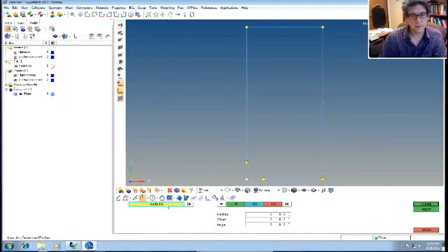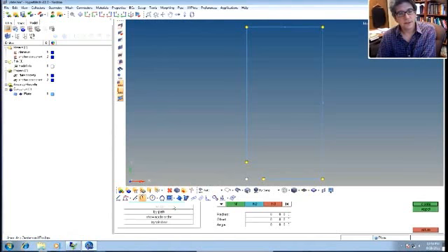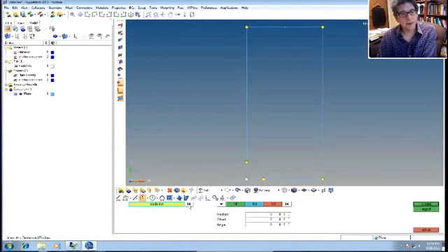That's this one. Yeah, I should talk about this a little bit. This is kind of weird. This always pops up in Hypermesh. You can have different select options here, and then this button actually clears the list. You can see if I pick the center point, there it goes. So highlight that node list, and then click the center point.